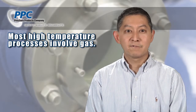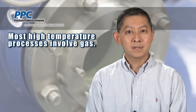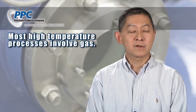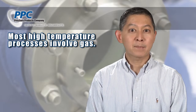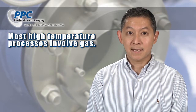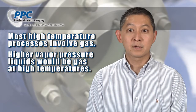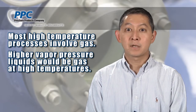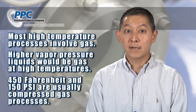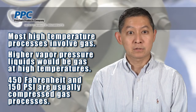On the other hand, very few actual sight glasses are used with very high temperature liquids like that. Let's use a little common sense here. Most processes that see 450 Fahrenheit involve substances that have much higher vapor pressures than high temperature oils. So the process fluid is a pressurized gas. For water or water-based liquids, the vapor pressure at this temperature is over 400 psi. If you're operating at a 150 psi process and 450 Fahrenheit, you have steam. And of course, lots of processes use compressed gases at these conditions.